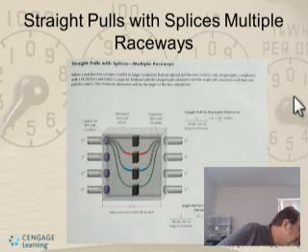Where a junction box contains 4-gauge or larger conductors that are spliced, and the box contains only straight pulls, compliance with 314.28(A)(1) and (A)(2) is required. Perform both the straight pull calculations and the angle pull calculations, and then compare the results. The minimum dimension will be the larger of the two calculations.